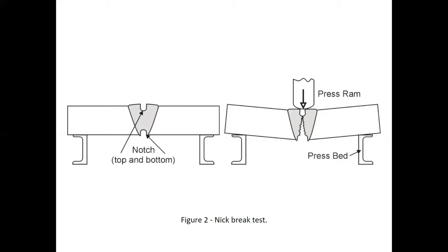There's a bunch of different tests we can do. I don't like to do destructive tests in here. Firstly, I don't have the equipment for it. To create the equipment will cost some money, but also if we're building this equipment, we don't have the guaranteed safety that a lot of these pre-manufactured pieces have gone through the testing for. So it's a safety issue too. We do cut up some welds and etch them with some nitric acid, but other than that, we don't get too destructive as far as destructive testing.